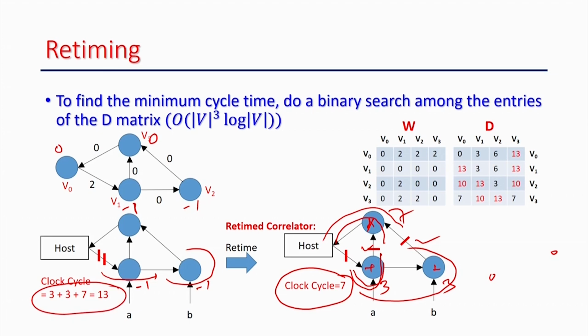So, you can see that using this retiming algorithm I actually solved this problem, right. I find out the value of this variable such that this R0, RV0, RV1 and R2 such that I actually reach the circuit which is my target, and I can reach the clock period of 7, right. So, you understand the overall flow.